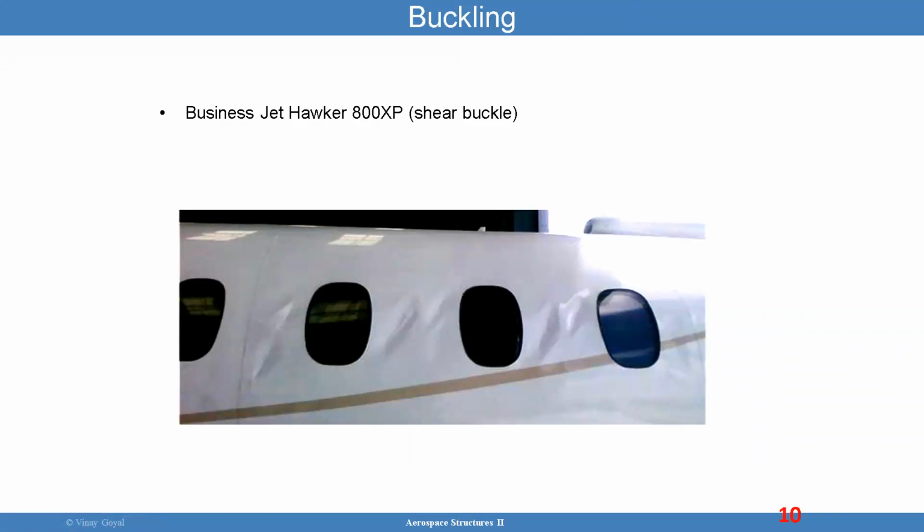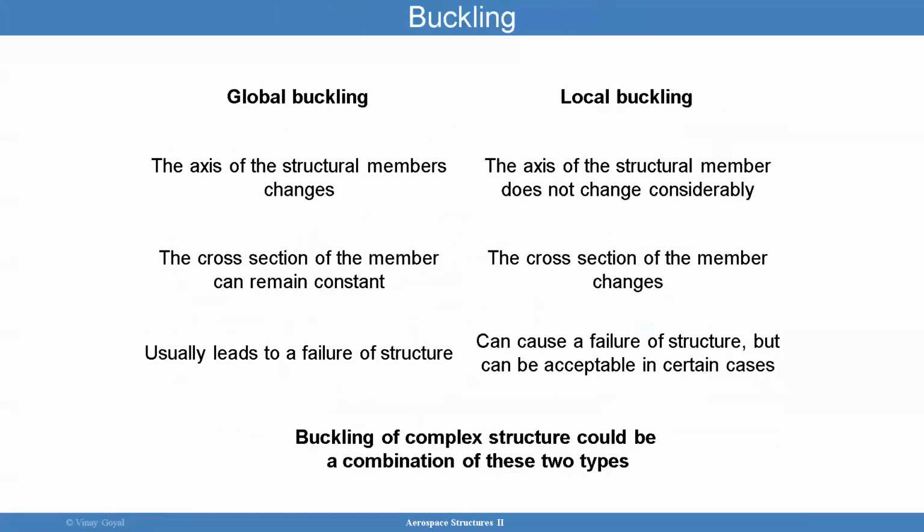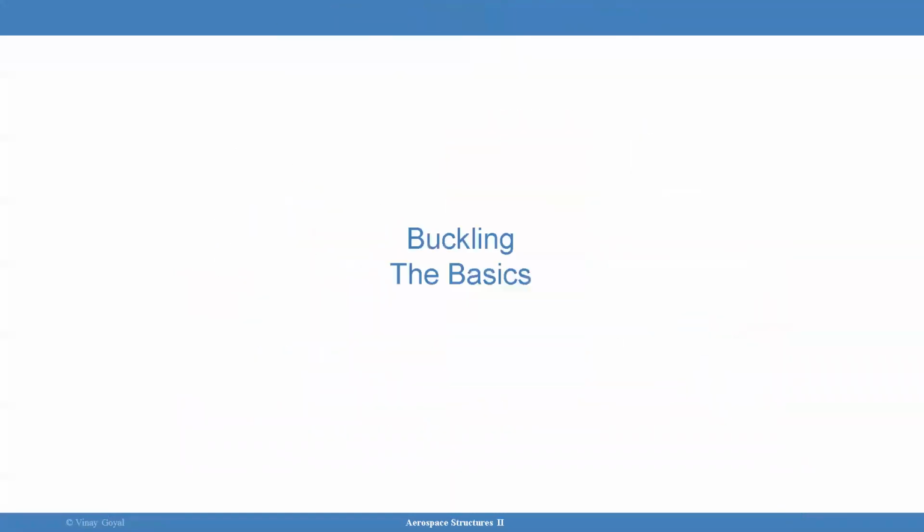If the local buckling affects the functional performance of the part, that can be a problem. Local buckling can also precipitate global buckling. So we want to make sure, as we increase the load in the testing or analysis, that the local buckling events are not too close to the global buckling events, because then you're hitting it too close, and that can be a problem for the design.